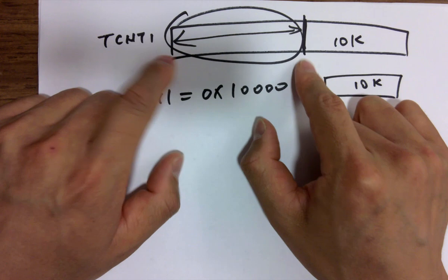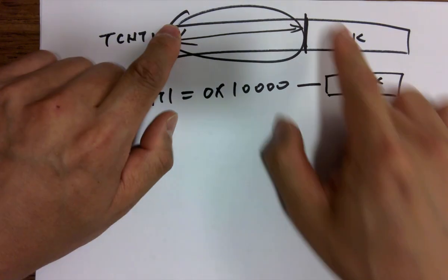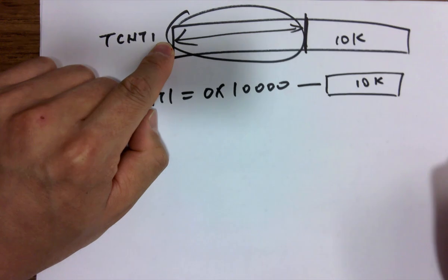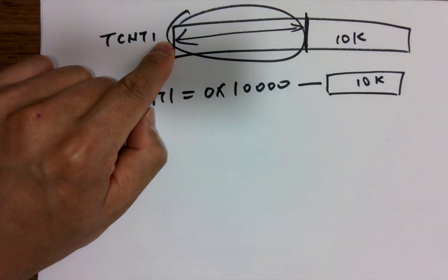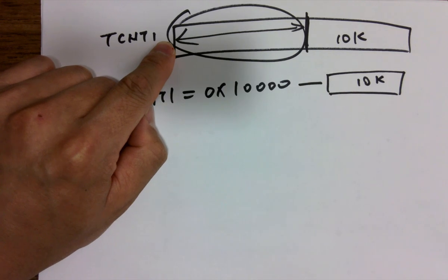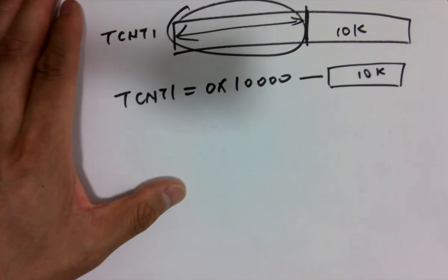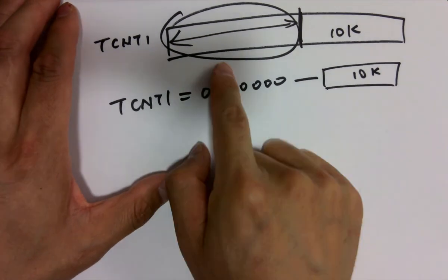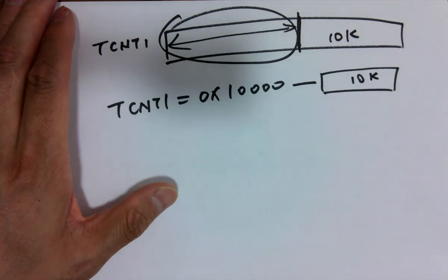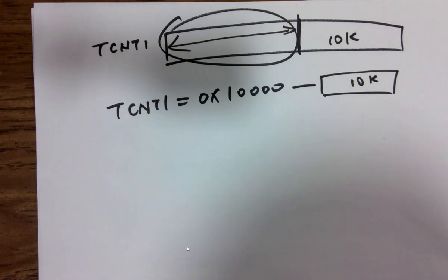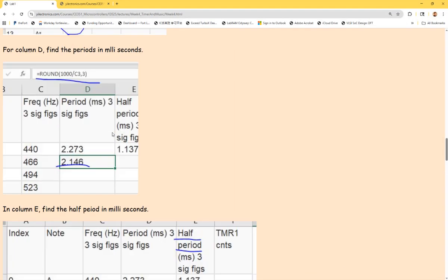All right, so you assign this offset to the counter, so it has something to start with. So start counting from here, and then just need to finish the rest, the 10K counts, which is exactly 800 hertz, or whatever the time, the half period time, with that certain frequency. Any question on this? So every time you start a timer, you give a start value immediately. Okay. Now let's come back to the code.